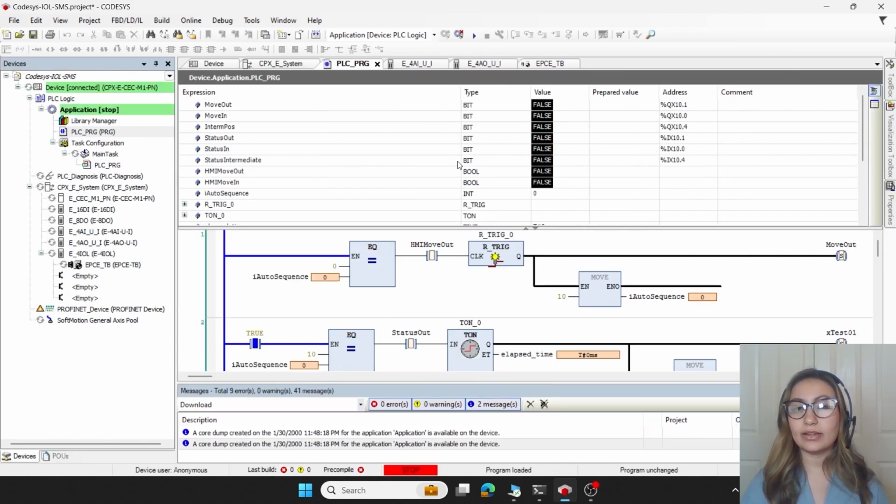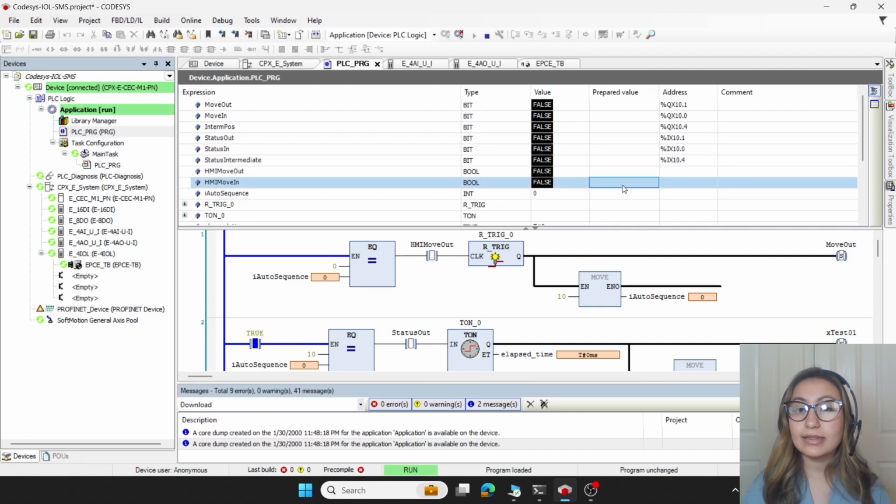It might give you a signal to log in with the download, but what I'm going to do is I'm going to run my program. And if you recall, when we were doing the wiring configuration, our CQ LED was actually a yellow color. So in order to reference that on CODESYS, now that it's running, I'm going to set this to true. And I'm going to hit Control F7 on my keyboard so that I can move the actuator out, and that way it knows that it's referenced. So my CQ should now turn green once my actuator moves. So I'll hit Control F7.